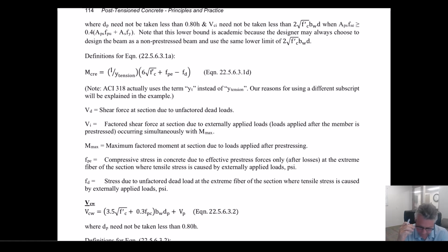It's a true story. So that's a very complicated thing to actually have to figure out, particularly when we get to post-tension concrete and when we add the complication of the fact that we have columns up above that are not there typically during the construction process, when the initial dead load is applied and when the pre-stressing is applied. Then that upper column is built later and the live load comes along and any additional dead load. So this can get complicated. You can have two different stiffness matrices that you're talking about based on whether or not you have a column or not for some of this loading.